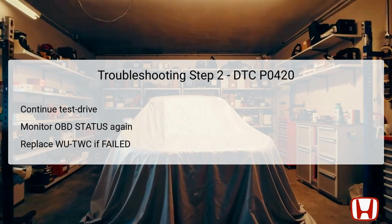If the HDS displays failed, it signals that the catalytic converter, specifically the warm-up TWC three-way catalyst, requires replacement. However, if the status indicates passed, it marks that the system is functioning as expected at that moment, while executing suggests that further driving is needed. If out of condition appears, it will necessitate a repeat of specified test conditions to ascertain component functionality.